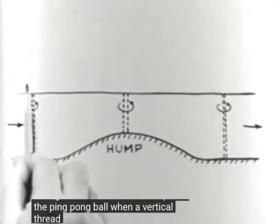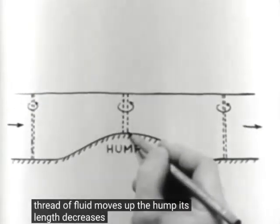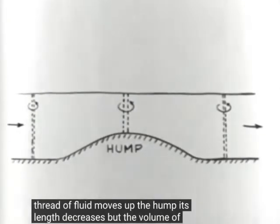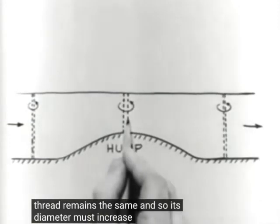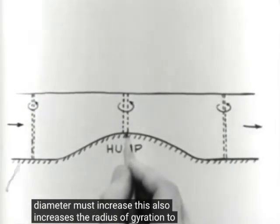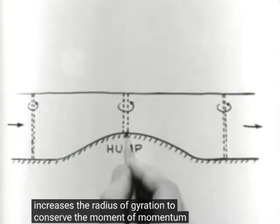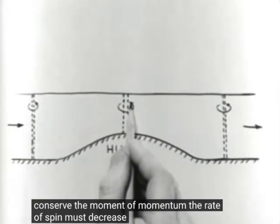When a vertical thread of fluid moves up the hump, its length decreases, but the volume of the thread remains the same, and so its diameter must increase. This also increases the radius of gyration. To conserve the moment of momentum, the rate of spin must decrease.